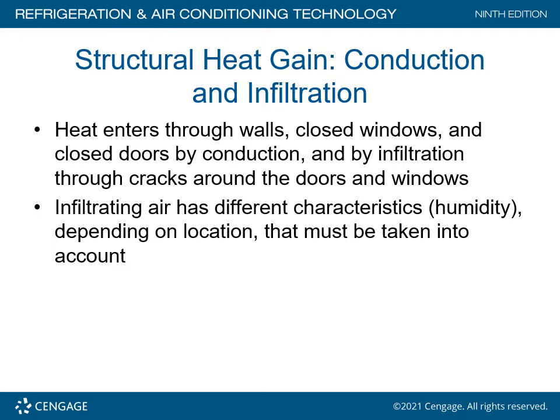One of the things on older houses, some people will elect to hire a company or a person to do what they call a heat loss, heat gain analysis of the structure. They'll use thermal imaging guns, visual inspection, construction techniques, and composite construction of any room additions.